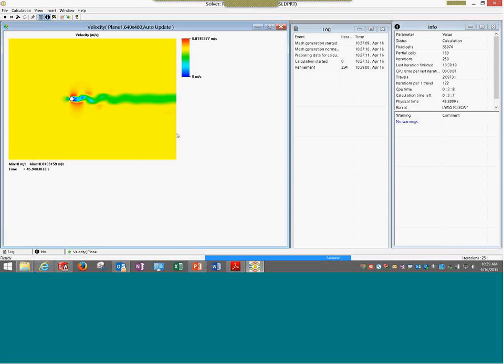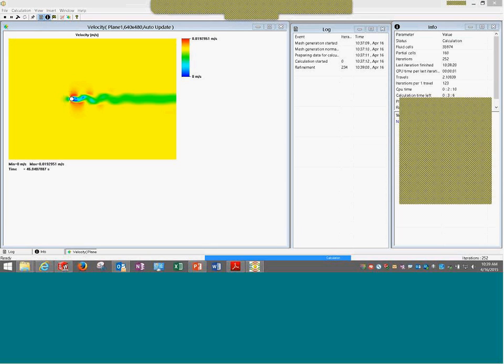Let me know if questions are there. Adaptive mesh decides where to refine. It is as simple as this: wherever there is a high level of turbulence, or a high level of velocity change, it improves the mesh. That's it. If I relate it with simulation, there it is the stress difference, and it will refine the mesh at the location of high stress.